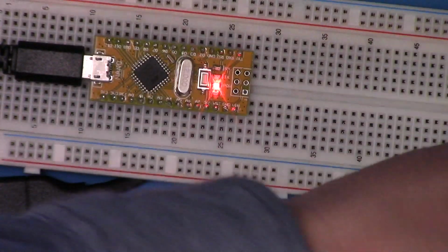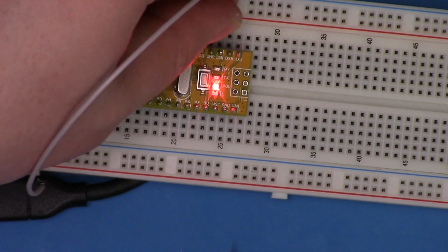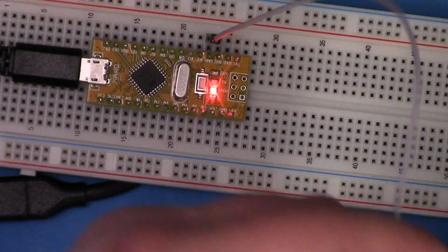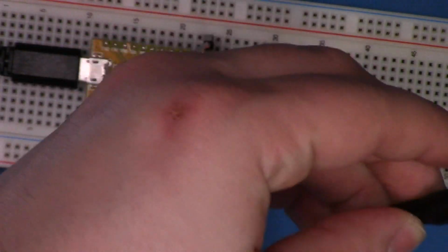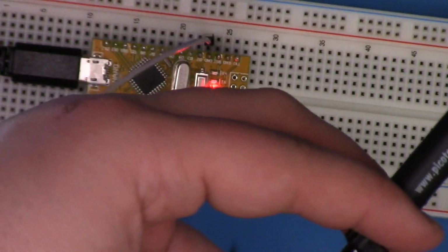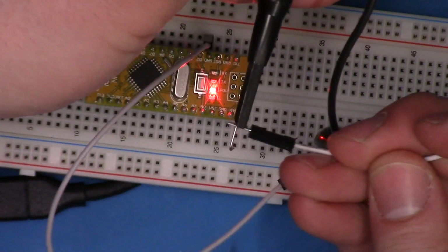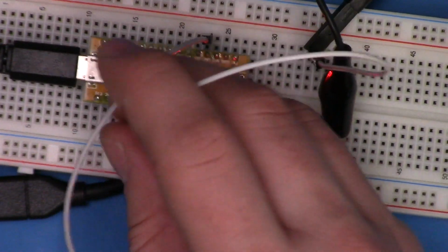And especially if you're using a standalone scope, you're going to need a ground connection. So we're going to ground it. And what you might find helpful, because maybe we don't want to hold it on, is I'll get another wire. I'm just going to plug it into this. And then I'm just going to plug that right into A0.